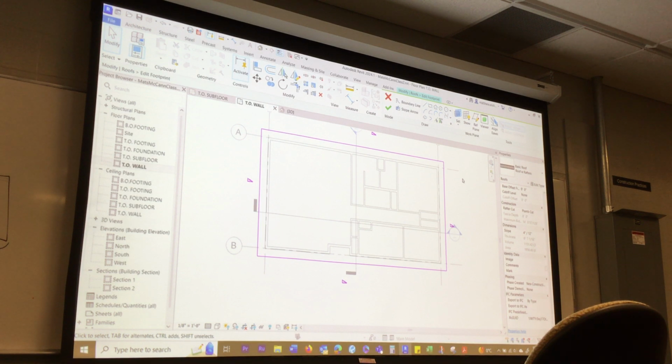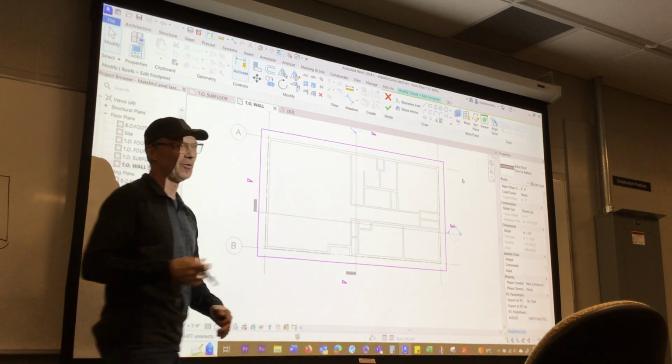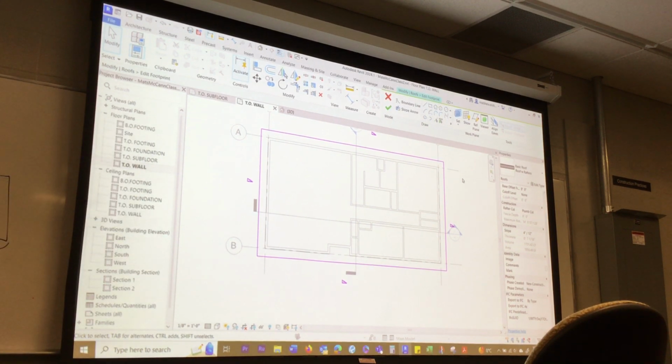Right? The reason is because when we add the stairs underneath, there's gonna be a couple of walls there. Mr. Drywaller is gonna drywall that right straight through. If there's a floor system in the way when you're walking down the stairs, you're gonna see the drywall come out into the stairwell. You don't want that. So that had to go back a half an inch. A lot of you didn't cut it properly, I'd say about half of you. Has to be cut at the framing. Again, you probably thought you were, but you probably weren't working in fine, and the drywall wasn't showing up. That's probably what a lot of that was. So just practice and patience.